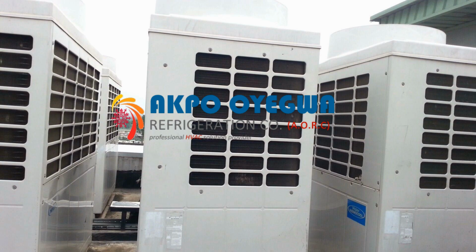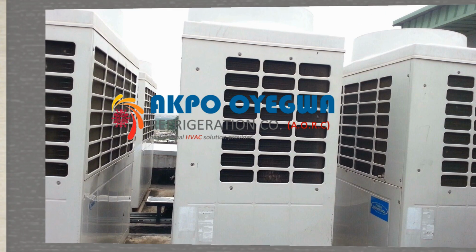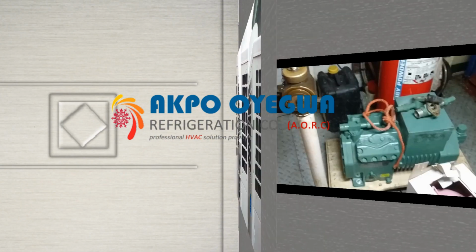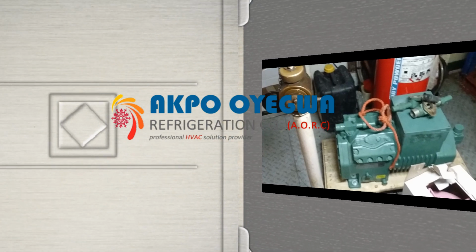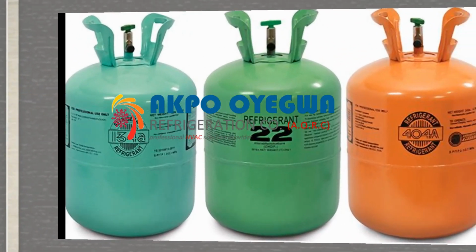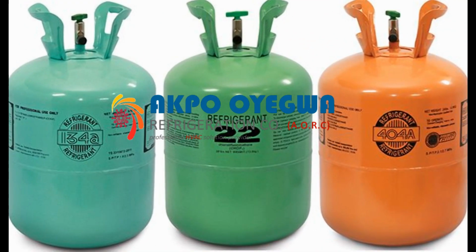2. R410A, Puron or Suva 410A. This refrigerant is a blend of two other refrigerants, R32 and R125, and is a common replacement for R22. It does not deplete the ozone layer and has a higher cooling capacity than R22.